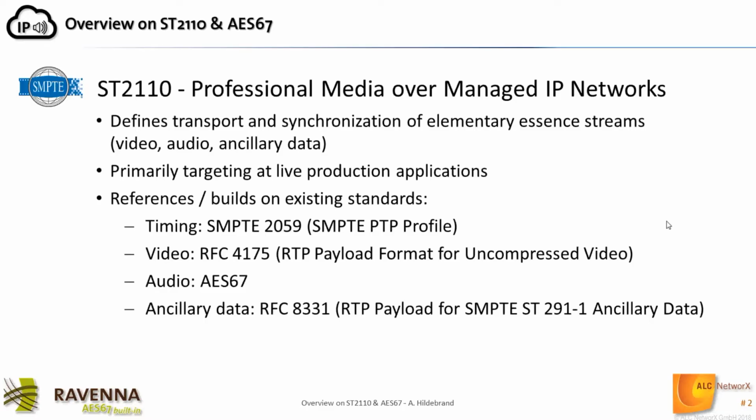The 2110 standard builds on or references other existing standards. For the timing part of 2110, the SMPTE 2059 standard is referenced, which in turn is a profile definition on the well-known PTP, IEEE 1588-2008 standard. For the video transport, RFC 4175, a standard for uncompressed video payload, is referenced. For the audio part, the AES67 standard is referenced. And for the ancillary data transport, a new standard from the IETF, RFC 8331, is referenced within 2110.